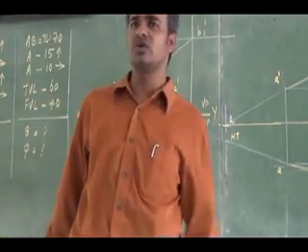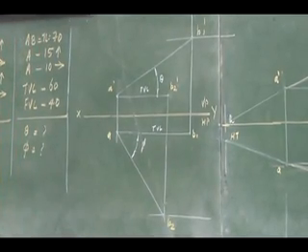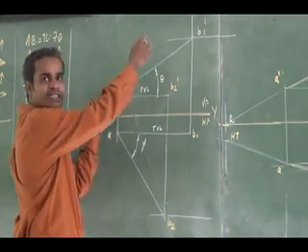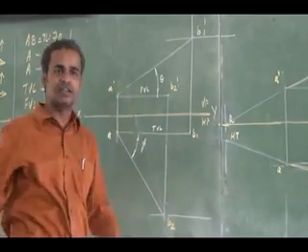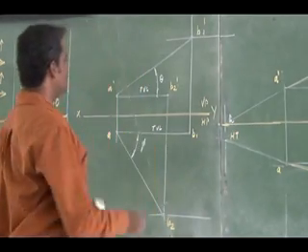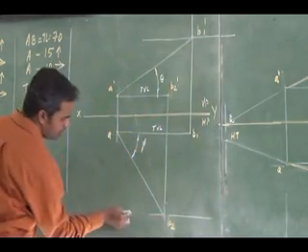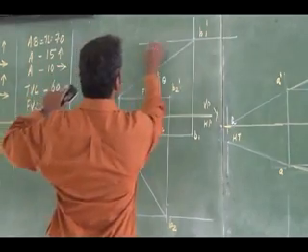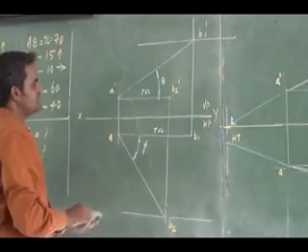You are asked to draw the projection also. Then how can I draw the projection from this stage? I can tilt the front view length to the top locus and the top view length to the bottom locus. Joining that, I will get the final front view and top view. So I have my two loci, top and bottom. Just I can rotate it.